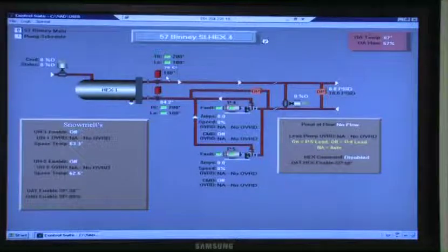That is all the glycol areas. It's gonna maintain 180, and the differential pressure set point of 10, which is on the far right. That DP valve is on the second floor, and it's gonna maintain differential pressure for that. Oh, really? That's on the second floor. Can you write that down there, Jimmy? Differential pressure valve. Just put a note, second floor, where that's located. The sensor and the valve are located on the second floor.